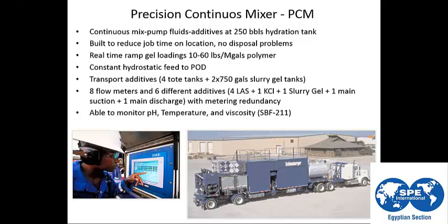So what are we mixing before starting the job? We are mixing the biocide, we are mixing the salt for shale inhibition, we are mixing the gelling agent. So we created what we call a linear gel. Then we use this linear gel to pump through the blender and mix the flying additives. What additives are mixed flying? The proppant, the crosslinker, the breaker.